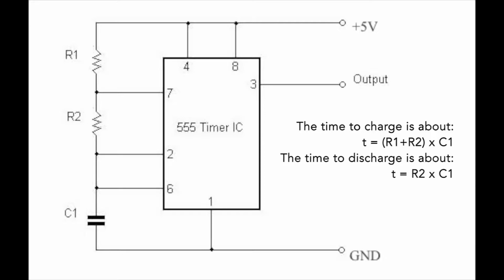At a certain voltage level, the 555 decides there is enough voltage on the cap, so it turns on a discharge transistor inside it. The capacitor now discharges via R2. The cap and R2 set the time taken for the discharge part of the oscillator cycle, so the capacitor slows down the rate of rise and the rate of fall of voltage.